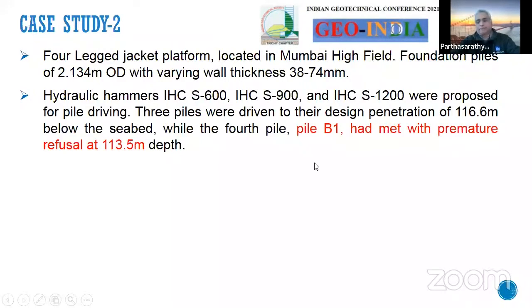the target penetration. I already mentioned the philosophy of the principal clients: if the piles are driven to target penetrations, because they have high quality geotechnical data, piles are accepted. But in this case, it was suspected that the hammer was not performing properly, and thus the piles were not accepted. So how can we do the remediation on this?